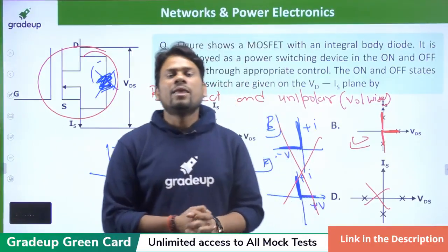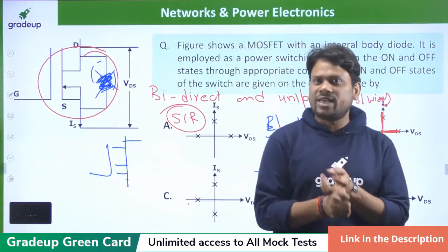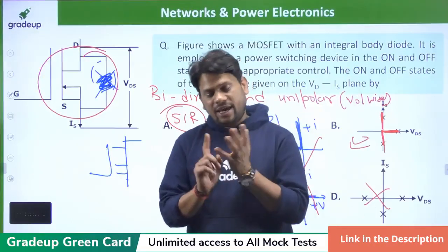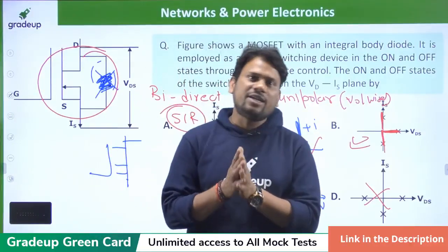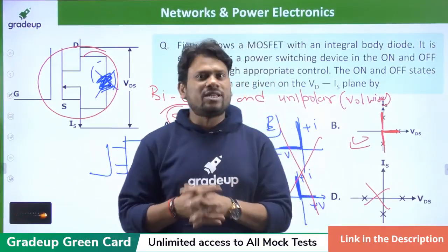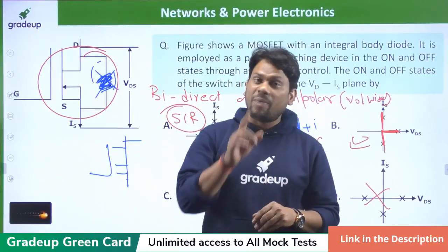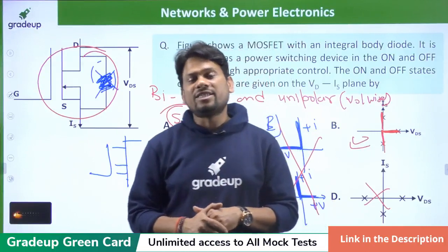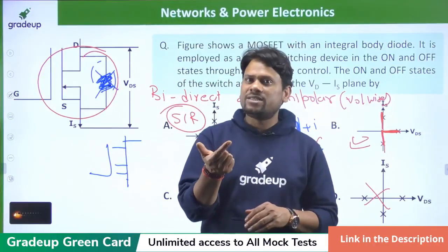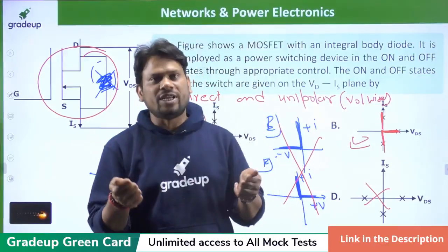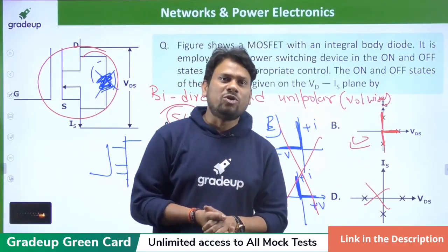Yeah, definitely. MOSFET and IGBT are voltage control devices; BJT, SCR, GTO, TRIAC, etc. are current control devices. You only have to keep this in mind, my dear friend: when we trigger our device by current, those types of devices will be current controlled. When we want to trigger our device by voltage, those types of devices will be voltage controlled. Okay, do discuss gate source voltage.